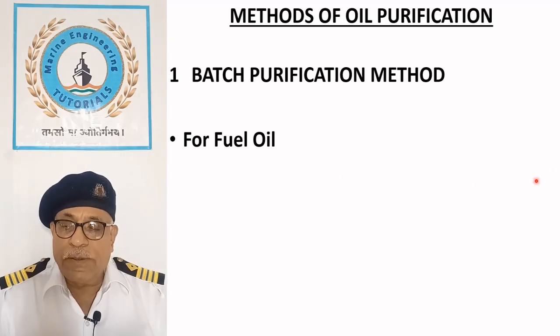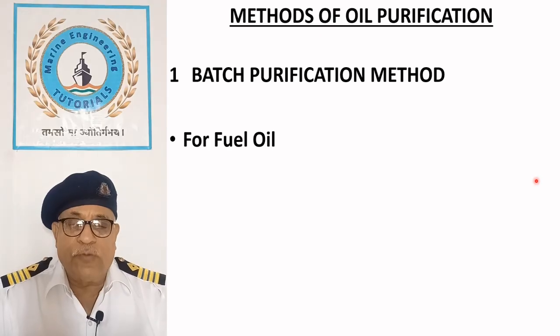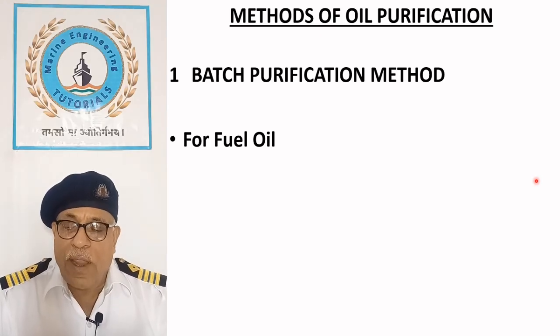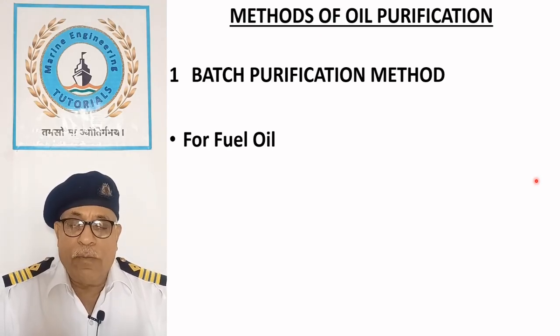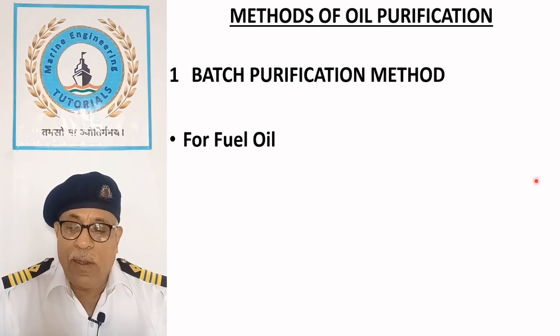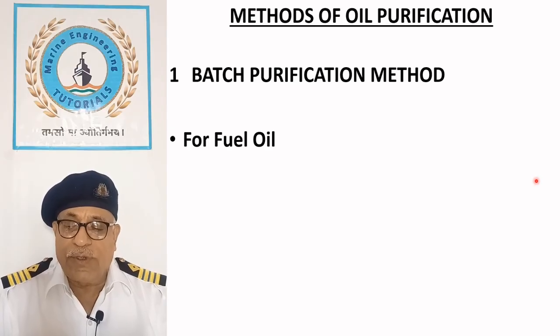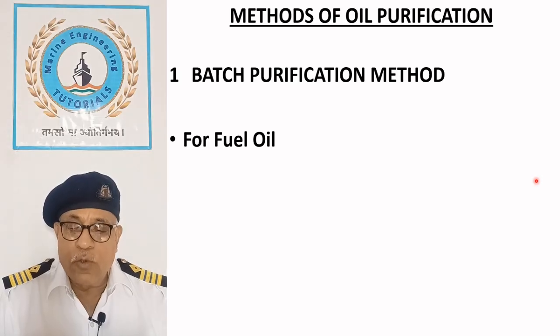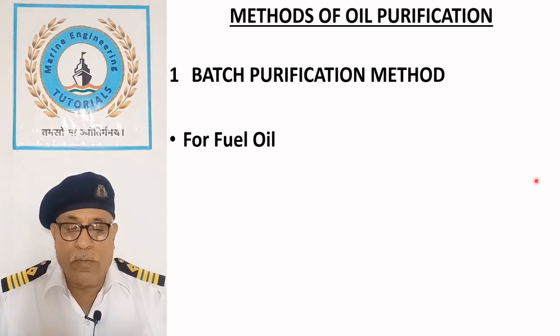In this process, unpurified oil is first transferred to the settling tank. From there, it is supplied to the clarifier for purification. The purified oil is then delivered to the service tank, from which it is finally supplied to the diesel engine.